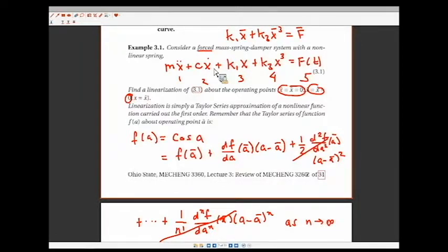That's linear. So the main thing is that if you have a linear term, it's going to be linear, and it's also going to cancel out when you apply the static equilibrium as well. So depending on how you learned it, or maybe you get really good at it, you see, all right, linear, I'm just going to cancel it. If you want to skip that step, that's fine, right? But this is showing the long form of why, when I take a linearized version of K1x, the K1x bar cancels out.